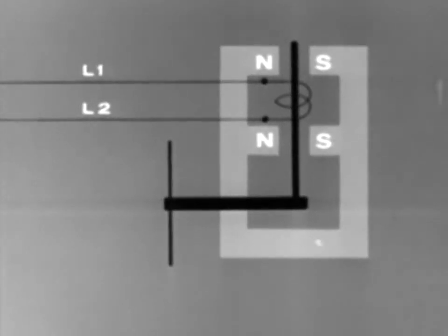For convenience, a second unit is placed in parallel across the line, giving us the simplest of all telephone systems, the sound-powered system, so called because it draws its energy directly from the transmitted sound. The chief advantage of the sound-powered system is also its biggest limitation. If, for instance, our line is extended beyond a certain range, the received signal will fade out and become unintelligible. The resistance in our line becomes too great to be overcome by the weak energy of the sound-powered transmitter.